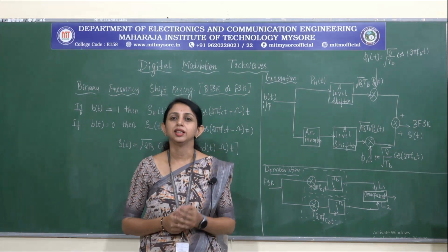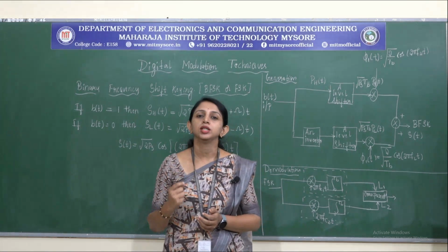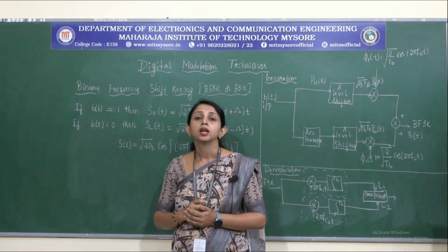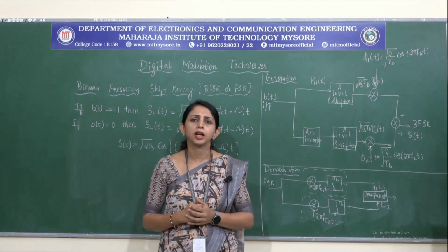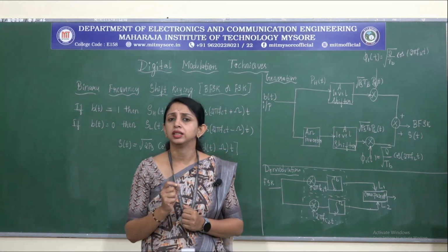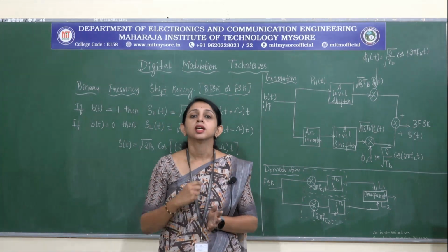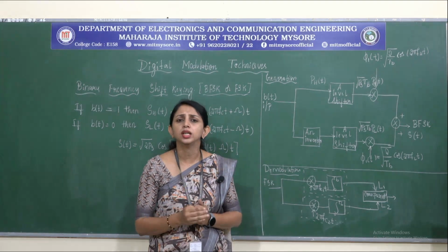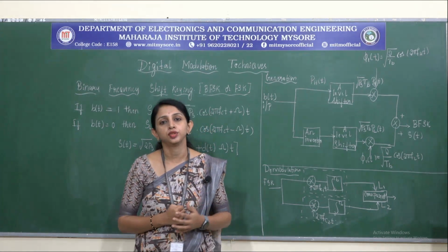Now I am going to explain another method of digital modulation technique, which is frequency shift keying or binary frequency shift keying, which is FSK. Before this, why are we moving to FSK? Because there is some drawback with respect to ASK. ASK is very sensitive to noise and it is able to handle only lower bit rates. Since it has less immunity to noise and is capable of handling only lower bit rates, we are moving to the next technique, which is frequency shift keying.